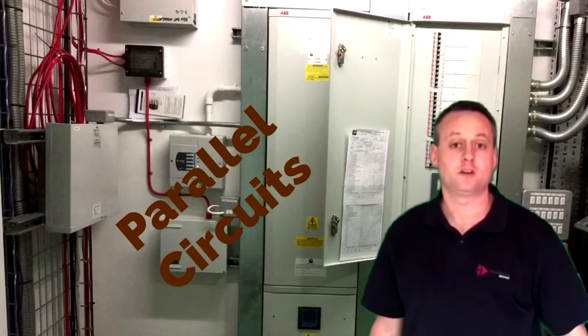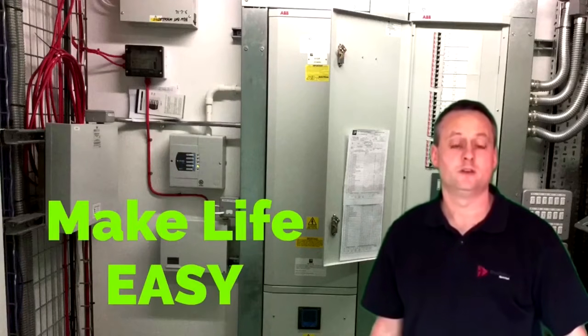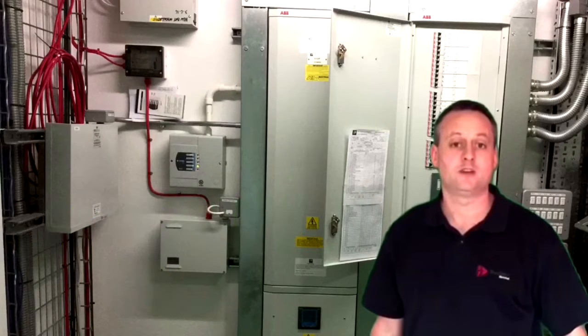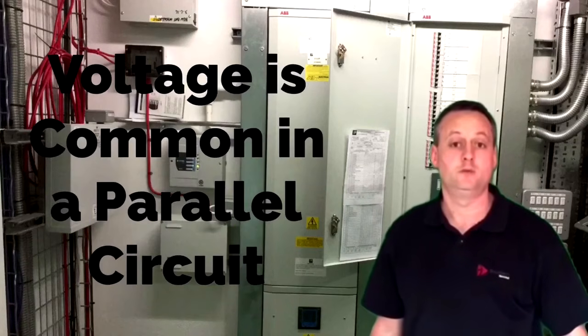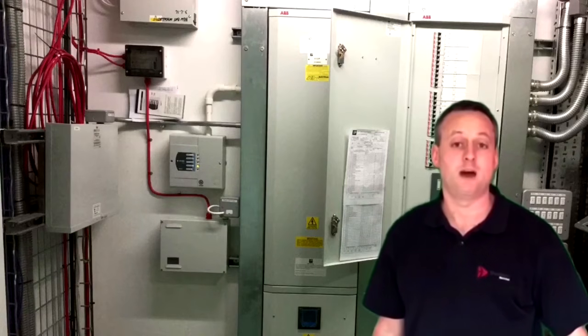Parallel circuits are slightly more involved, but again, we're looking for a default position in order to answer some of those multi-choice questions. The common element in a parallel circuit is voltage. Voltage will appear across each of the loads exactly the same as the supply voltage. The total resistance in a parallel circuit is not as straightforward as simply adding them together. We looked at the formulas in the classroom, and again, I would expect you to try and remember those to get the higher level of pass, the distinction level of pass.